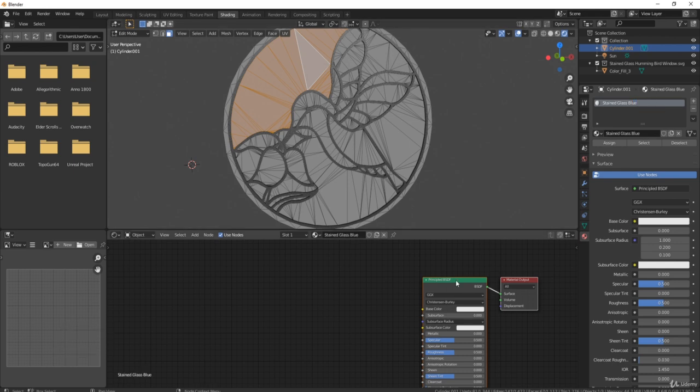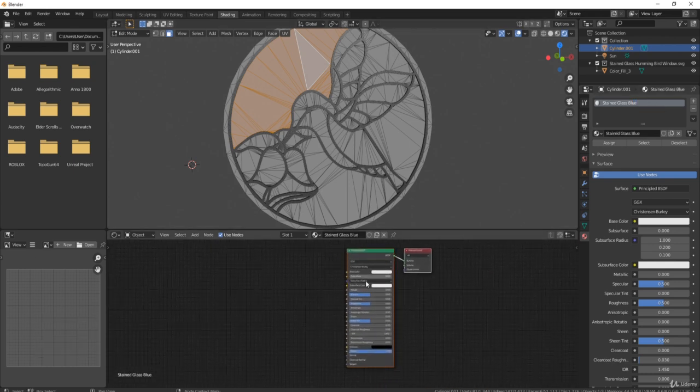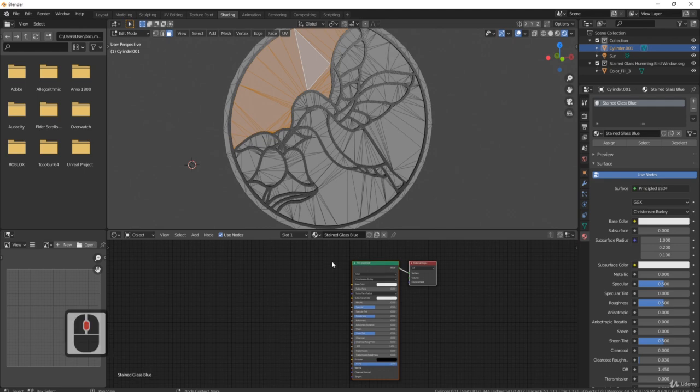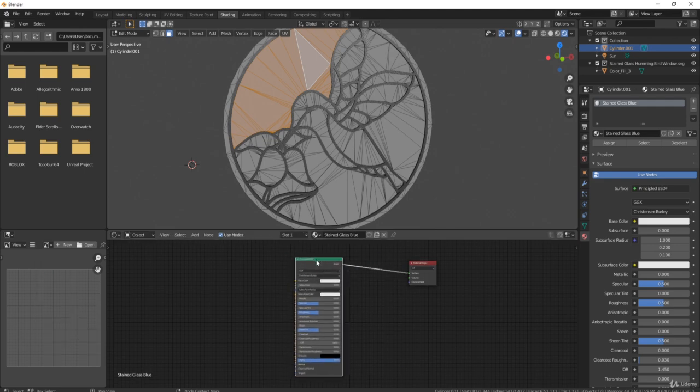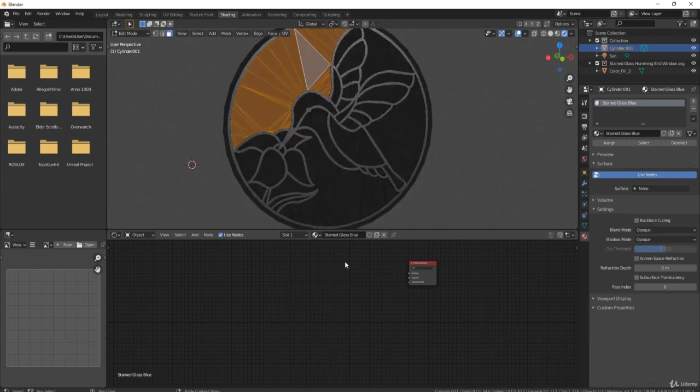And then I'm going to come to my shading panel here. I said that this principled was a supernode, but on this occasion we're going to simply click on it and click delete, and it will go black, but don't worry about that. Alright, so let's build this next material. The first thing is we're going to need a geometry node to tell Blender where each of these islands are.